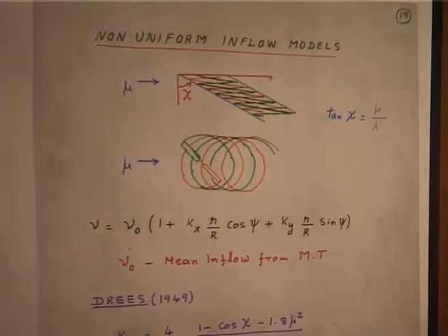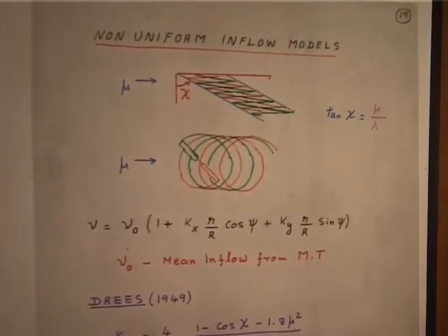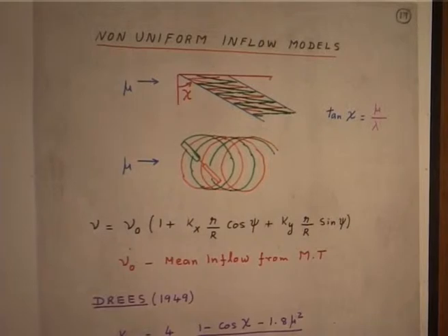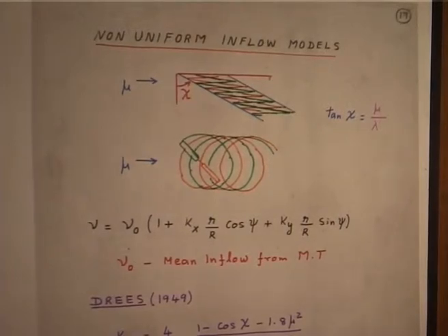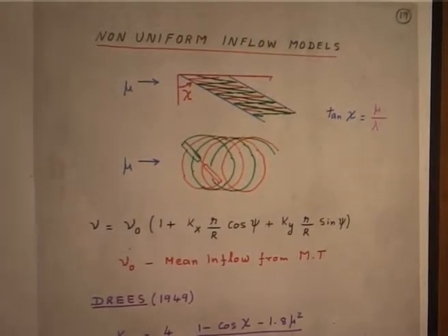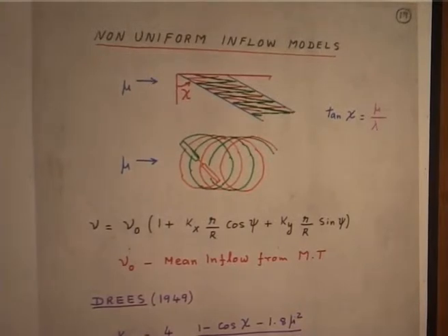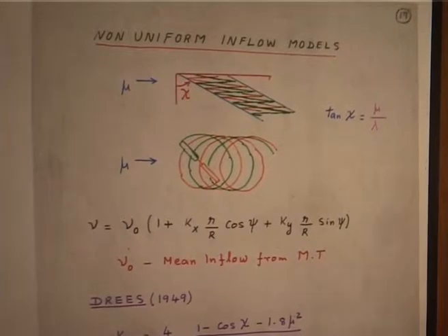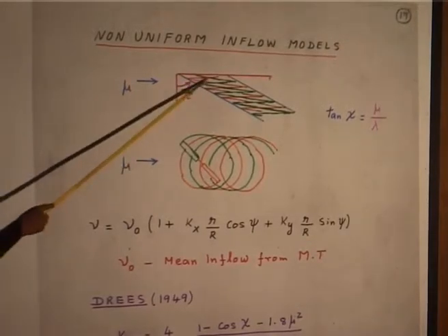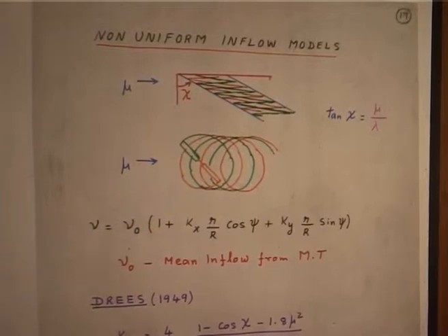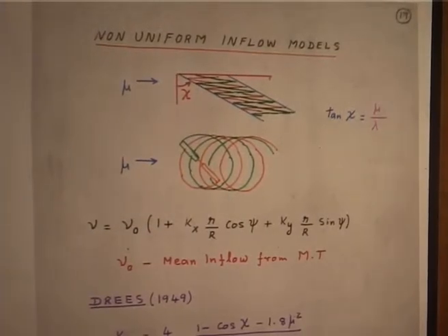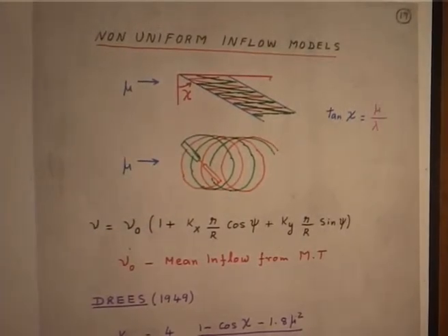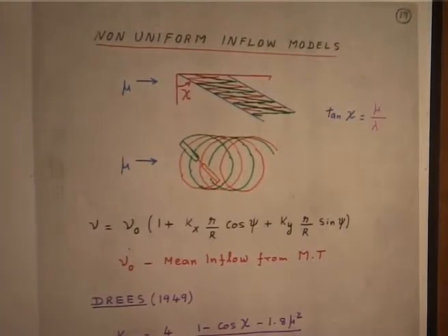But if you assume that the loading is constant, that means the circulation gamma is constant over the span of the blade, then you will have only tip vortex, okay, and the tip vortex is what is shown here. Each blade will give one, and they may interact with the other blade. So you will have a lot of helix intertwined.